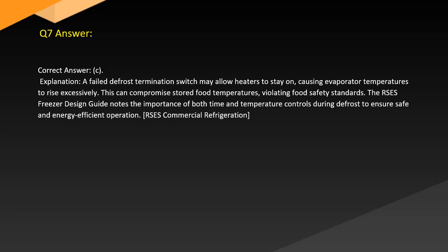Answer. Correct answer: C. Explanation. A failed defrost termination switch may allow heaters to stay on, causing evaporator temperatures to rise excessively. This can compromise stored food temperatures, violating food safety standards. The RSES Freezer Design Guide notes the importance of both time and temperature controls during defrost to ensure safe and energy-efficient operation. RSES Commercial Refrigeration.